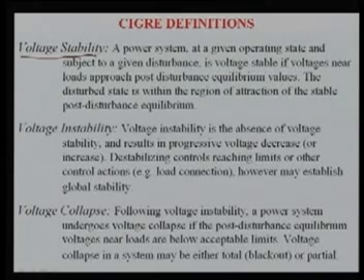Here in the voltage instability, what happens? There is a possibility that the voltage of a certain area or zone may increase or decrease heavily, and that may destabilize the control actions. We have a lot of devices that work on voltage measurement. If the voltage is low, an under voltage relay may pick up and give a trip command for load shedding. Because under voltage or under frequency relays are there, and they normally go for load shedding, so it may go for load disconnection. Then it is called voltage instability, meaning the voltage has gone excessively down or higher than its prescribed limit.